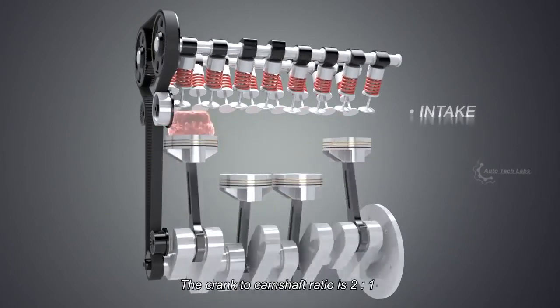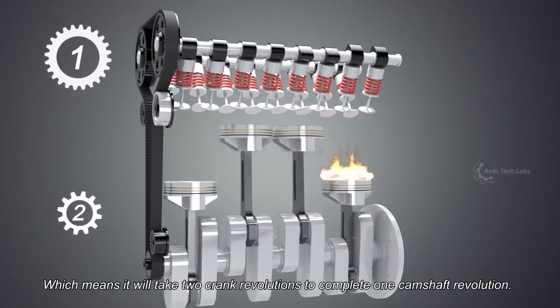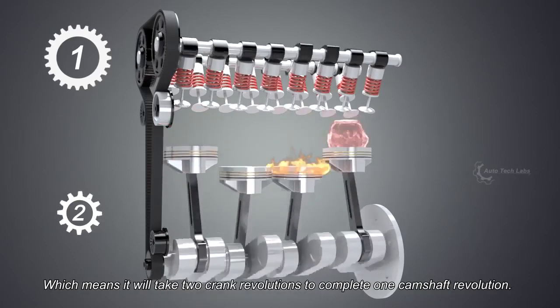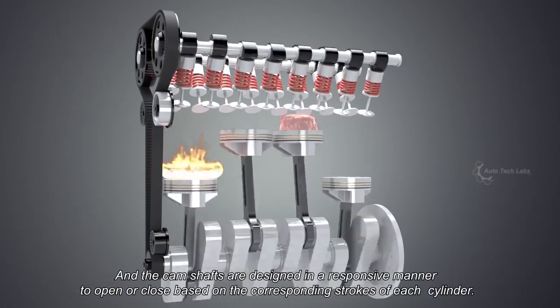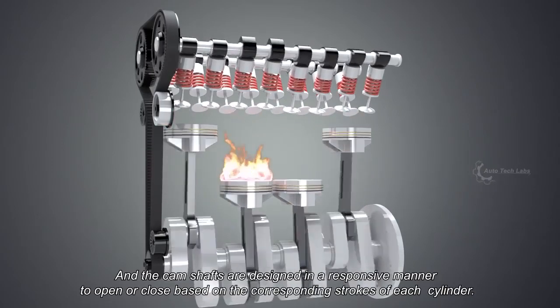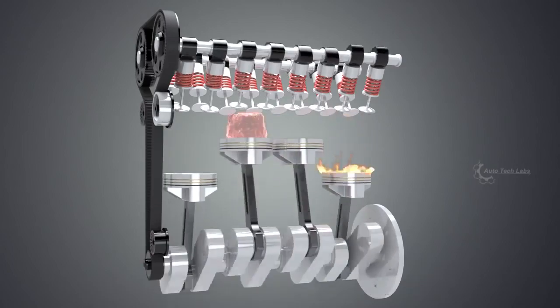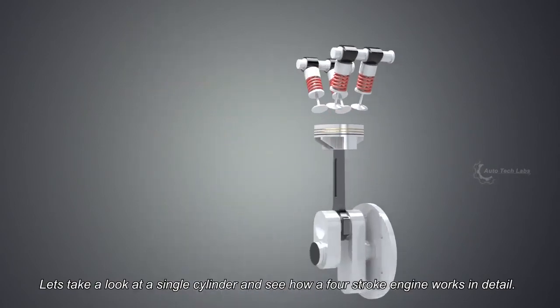The crank-to-camshaft ratio is 2:1, which means it will take 2 crank revolutions to complete 1 camshaft revolution. And the camshafts are designed in a responsive manner to open or close based on the corresponding strokes of each cylinder. Let's take a look at a single cylinder and see how a 4-stroke engine works in detail.